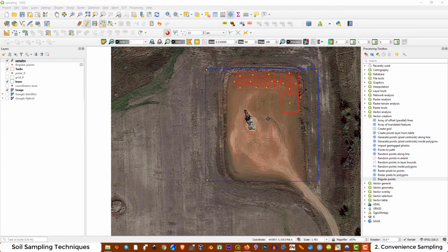As the goal of this project is related to identify any impacted soils related with the former tanks in this area, I decided to take just the criteria based on the location of the petroleum facilities. But maybe if you are also interested to identify any impacts in the wall center, maybe you are going to place some of the samples over here. But it's not this case. I want to just investigate this area over here.